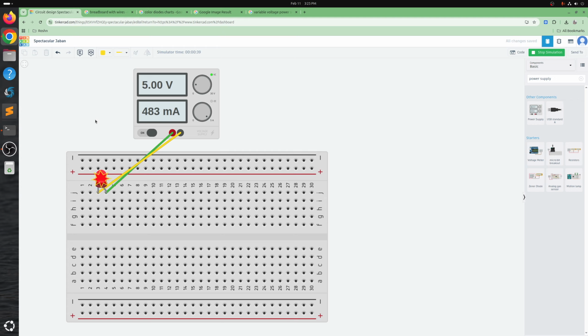But in real time, what you will see is even if the chart is saying 1.8 or 1.6, the LED might start blinking at lower values than that. So if the chart is saying 1.8, the LED might start blinking at 1.75 or 1.7. But in the simulator, as it's done programmatically, it might blink at exactly the same value. So now let us just turn the